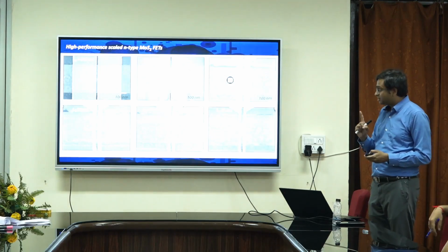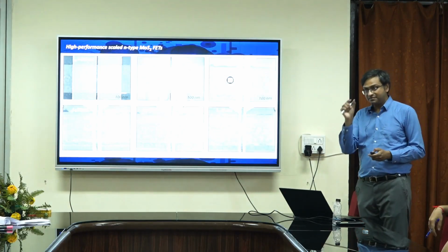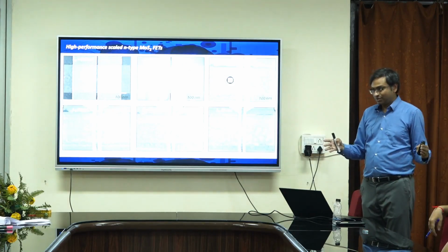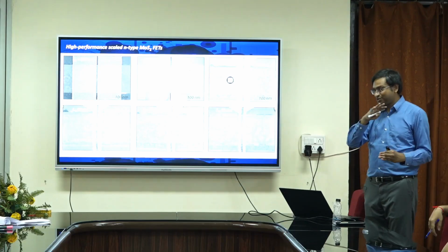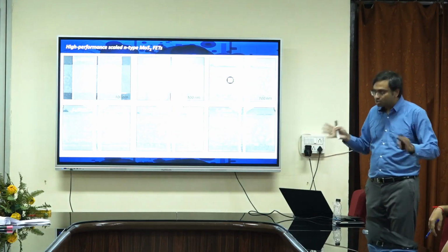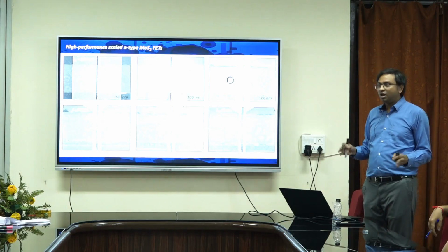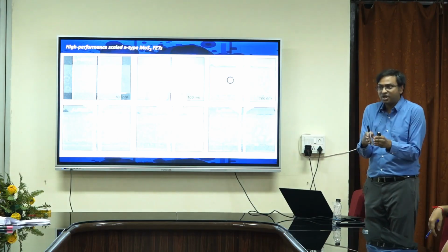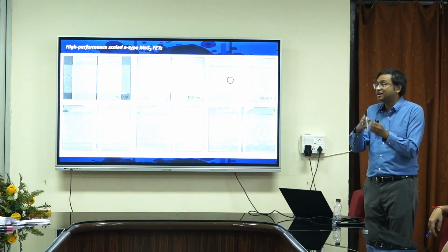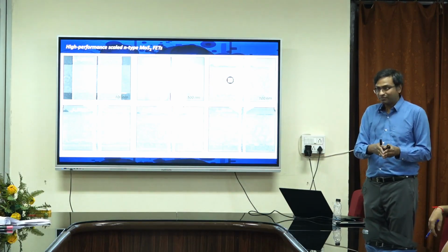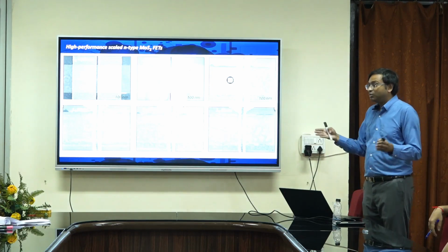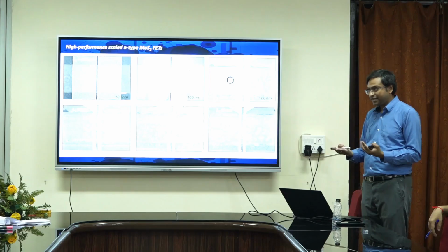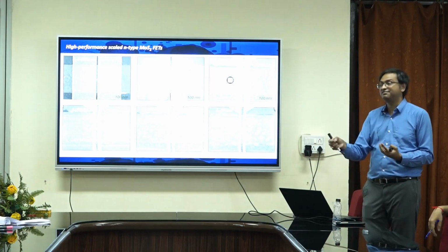But as I told you, all these studies which achieved very low contact resistance achieved it for a big contact, right? We are going back to our drawing room and now asking the question: okay, I choose antimony or I choose gold. Both are actually very good contacts, but what happens when I make the contact very small? That is still an unanswered question, because one may actually show better scaling compared to the other. At the end of the day I have to make the contact small and then achieve 50 ohm micrometers.